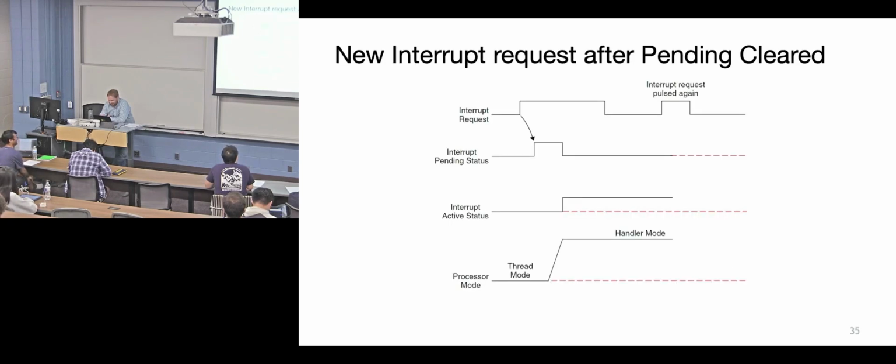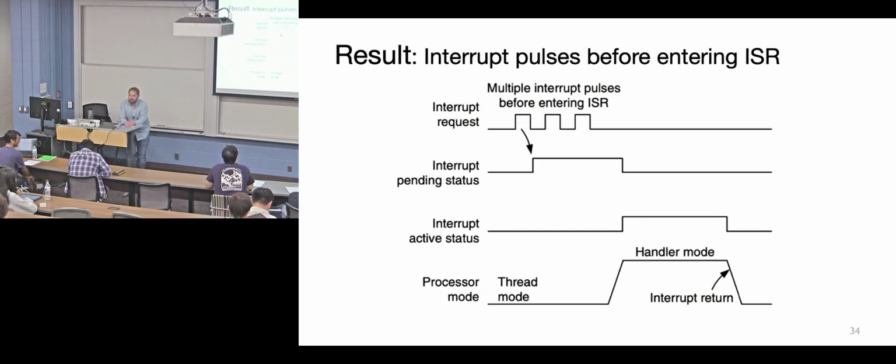Any other questions? So the big takeaway from this condition is that the architectural choice is not to count how many interrupts have occurred before you get to it. It just adds a lot of complexity. I'm sure some processor on the planet probably tries to do that. These are also fairly quick events. Here, the timescales have been kind of mushed around for the sake of the example. But it takes 12 cycles to get in here, and about 8 cycles just to stack. So it's not a common condition where you're going to even miss edges, at least not in this world.